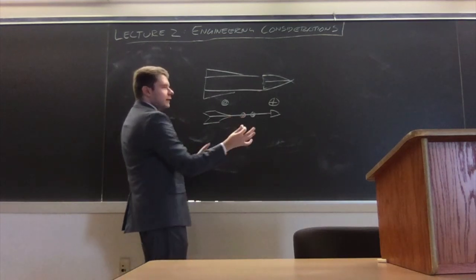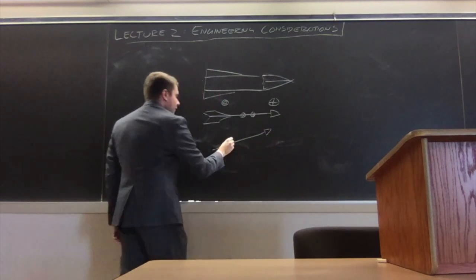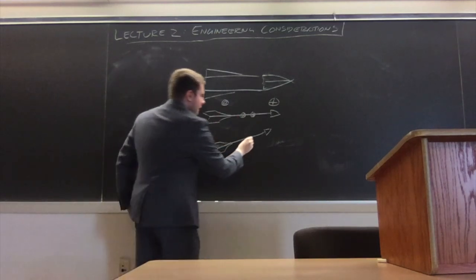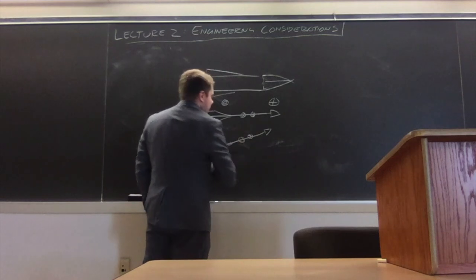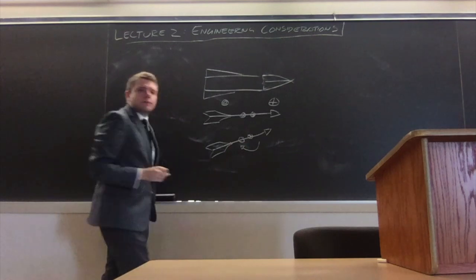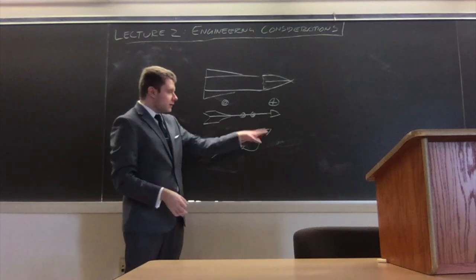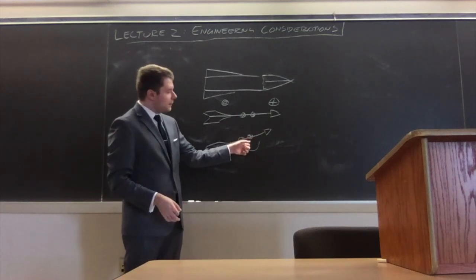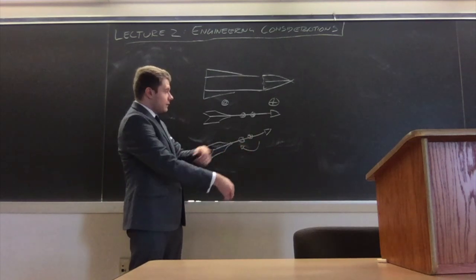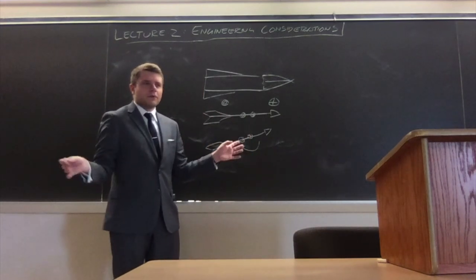It means that if the arrow goes a little bit out of alignment, in other words, if the arrow is disturbed by a breeze or a bird flying by or what have you, then your arrow will, of course, torque in response to that. But then your center of gravity and center of pressure are no longer aligned in the direction of flight. So it'll want to turn itself back to a stable position. And it will do that. It'll oscillate probably a little bit, but it will remain flying straight because it is automatically self-correcting. The aerodynamic forces are now offset from your center of gravity, so it torques around that center of gravity, and it rotates. It's self-correcting. It's self-stable. It's a beautiful, simple thing.